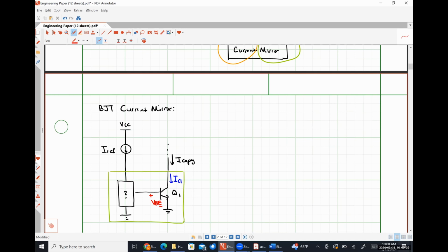So effectively, our output stage for this thing is nothing more than a voltage-controlled current source, which is exactly what a transistor does. Okay. We apply some input voltage, we generate some output current. That is what transistors do. Okay. So now let's talk about the black box with the question mark. Okay. So we need something that takes an input current in and provides us a very specific output voltage. So let's do a little bit of math here to sort that out.